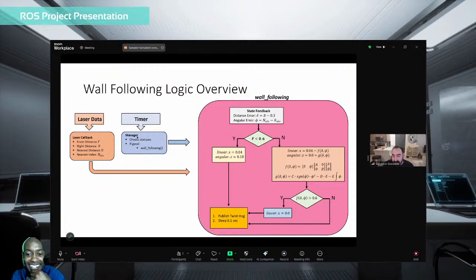And then ultimately those commands get published to Twist on this cmd_vel topic, and then I sleep. The reason I sleep is to prevent some chattering. There is this balance in the stability of the controller. Yeah. The real robot needs a little bit of time to respond and actually execute commands, rather than just think about it the whole time.